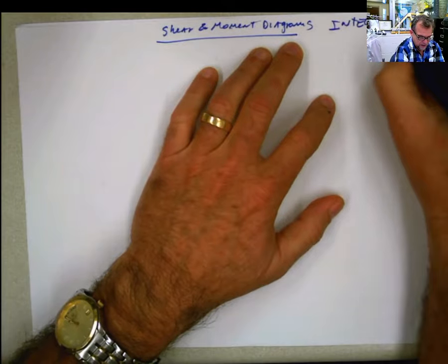Second, the next thing that we do is this. Now, span AC. In span AC, I'm going to say that the shear is the integral of the load, which changes with x, times dx.